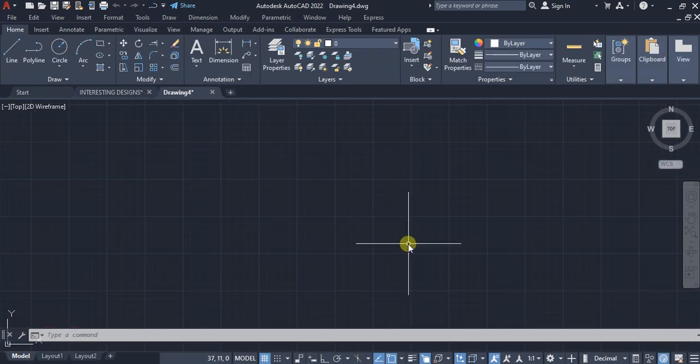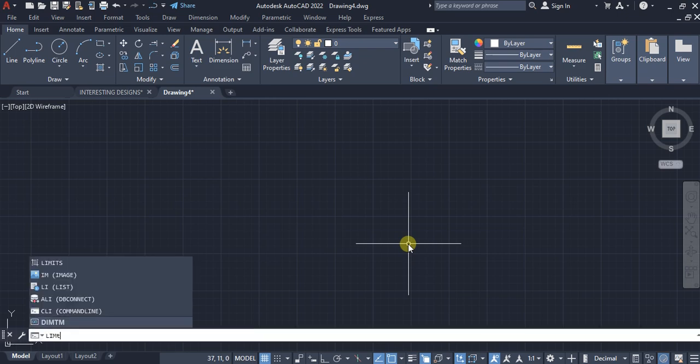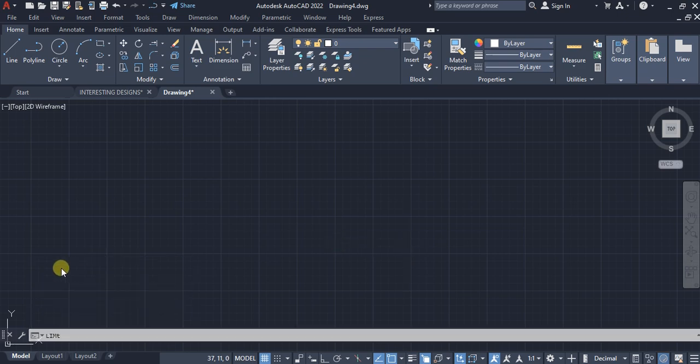Now to set up the drawing limit, it is either we go back to Format or we just use the shortcut by typing limits. So I'm just going to click on it to activate that, and then here you have limits. So AutoCAD is going to ask you to specify lower left corner, alright, 0, 0, enter.